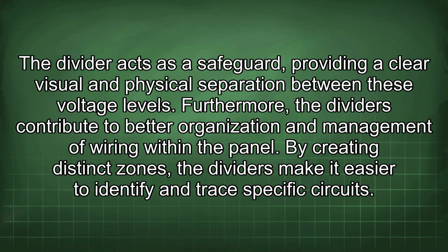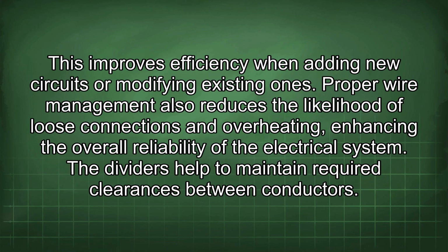Furthermore, the dividers contribute to better organization and management of wiring within the panel. By creating distinct zones, the dividers make it easier to identify and trace specific circuits. This improves efficiency when adding new circuits or modifying existing ones. Proper wire management also reduces the likelihood of loose connections and overheating, enhancing the overall reliability of the electrical system.